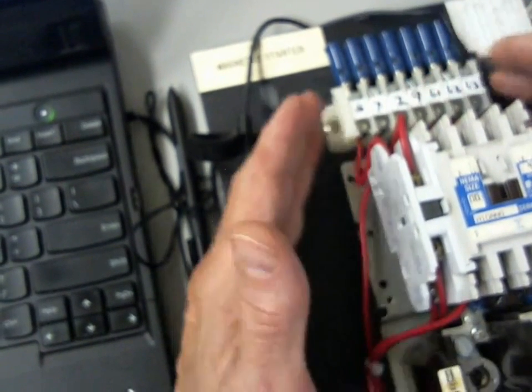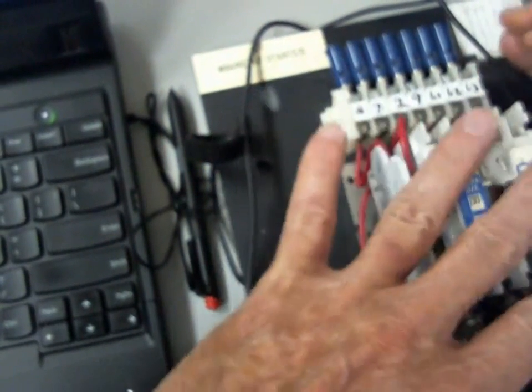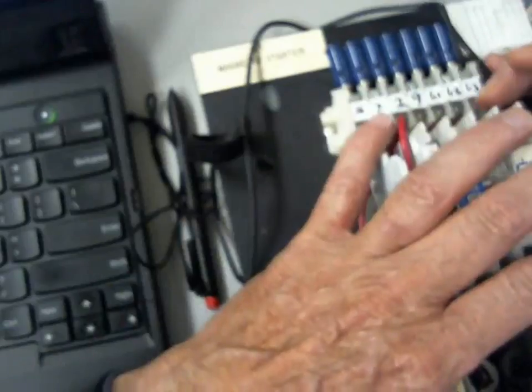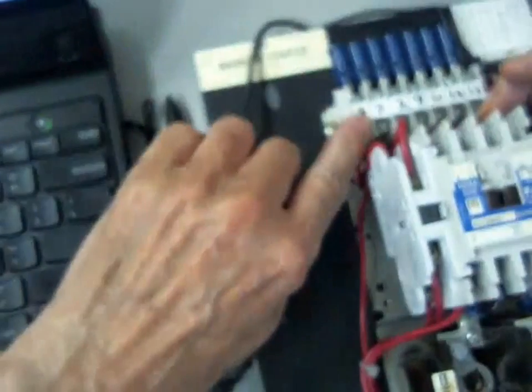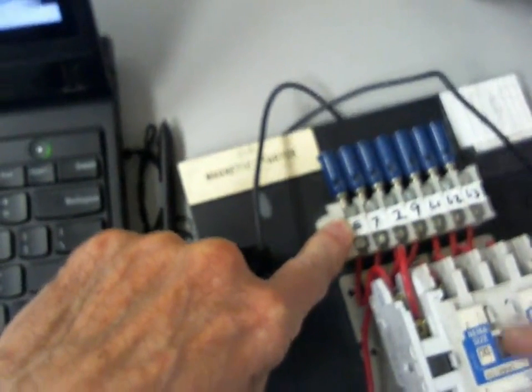And of course, what they do is just bring the manufacturer numbers out to a terminal board, right? So when you buy a device, all the terminals are going to be numbered or labeled. You do not assign those manufacturer numbers, but you have to know the manufacturer numbers to do what? To know how to wire them. So this is a 5, but wire number 53 might be coming into terminal 5. Well, you assigned the 53, right? Somebody in your group or whoever developed the wiring diagram assigned the 53. Who assigned the 5? The manufacturer of this relay.